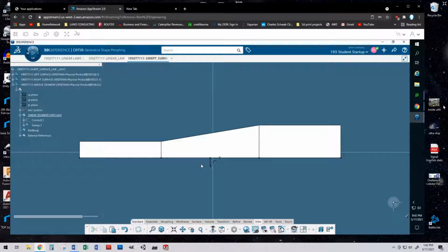Left buttock line. All buttock lines left are negative. All positive buttock lines are... All right buttock lines are positive. Where's the buttock line in the middle? Zero. Right down the middle. It's just buttock line. When you go right down the middle, it's not buttock line left or right. It's the buttock line. Buttock line left, buttock line right is what you guys need to get familiar with, the terms.